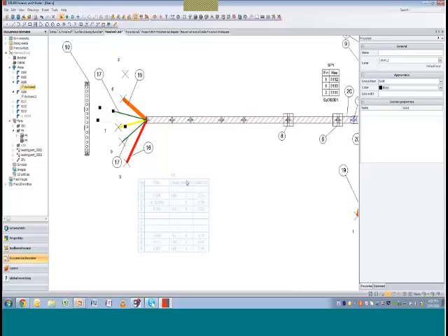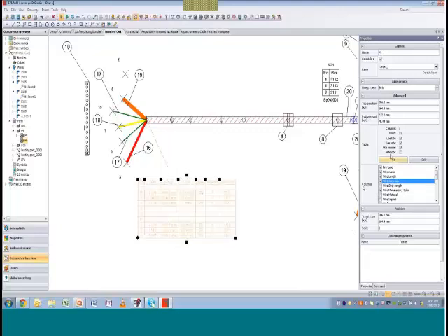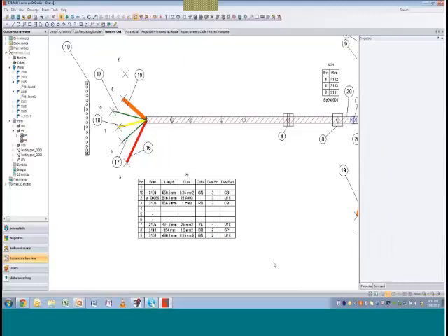So with our connector, here we have our P9. You can see that on our P9, these different connections are defined. If I want to see a little bit more information, I just click on the report, and over here in the columns, I can see all the different columns that are available to display for our report. For example, the wire length. I want to see the wire length and maybe the wire core size. Once I do that, I can see that my report has been updated, and we can see all the different wires. You can organize your pins.